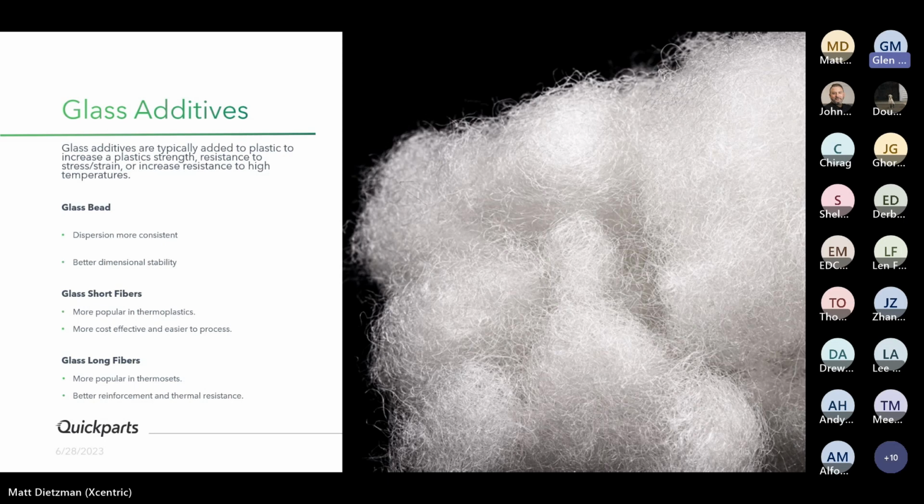Whereas a long fiber, better reinforcement and thermal resistance. They do get a little more finicky on the processing end of it. These fibers have to align themselves, and you have to process that a certain way with the proper temperature and speed and so forth. But yeah, here are basically your three different classes of glass additives.